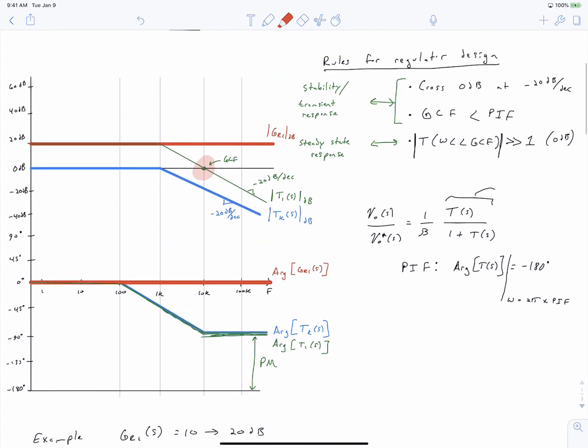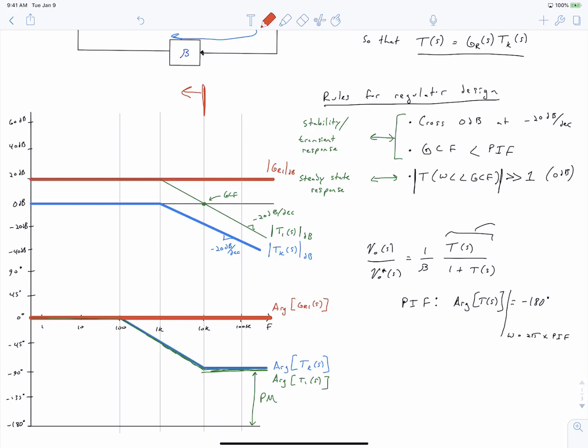And so we can make a general statement about this. We can say that at frequencies below this point, where we have a rather large gain, presumably, assuming that we follow this rule, our feedback is effective. But at frequencies above this point, where our loop gain keeps getting less and less, where we keep going down this path here, our feedback is not effective.